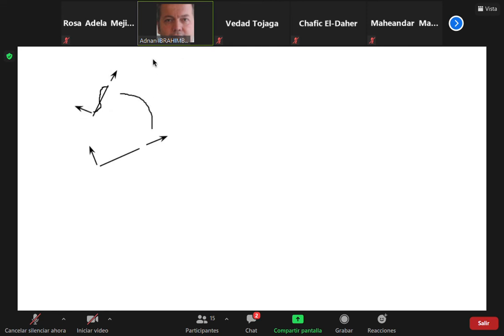Let me call this, what do you call it? Let's say alpha. Yeah, theta, whatever, doesn't matter. This is simply your large rotation, and these things here are a small deformation. So this is something that we call the co-rotational formulation, which means large rotation plus small deformation.